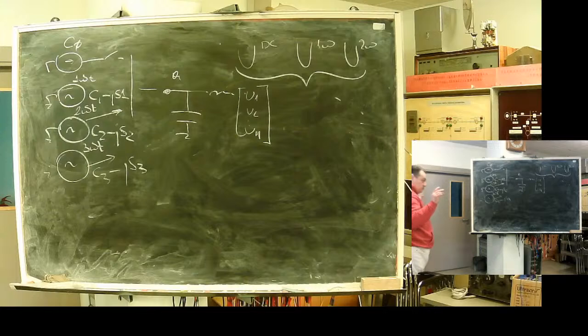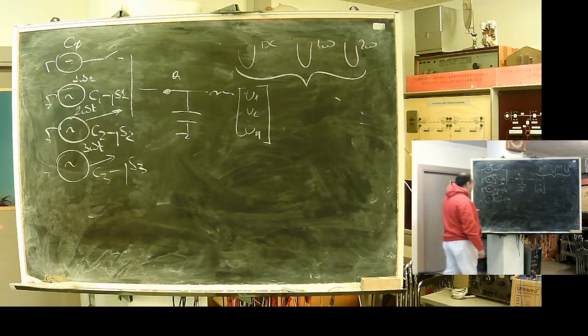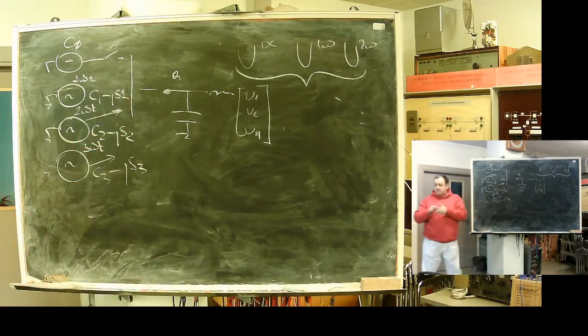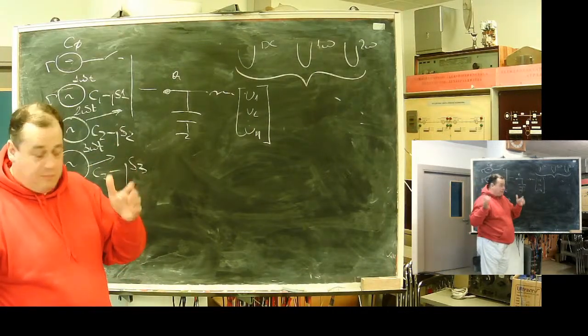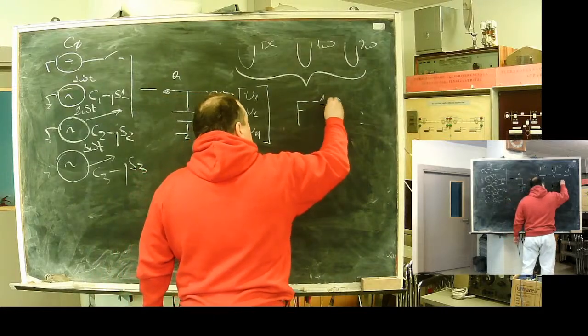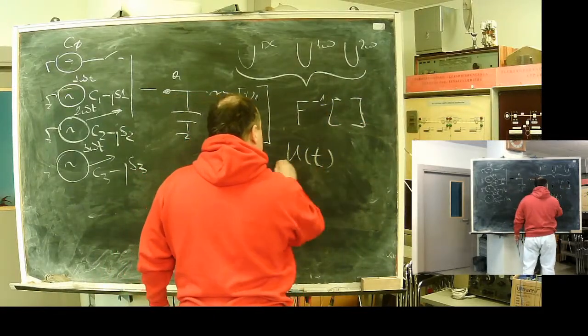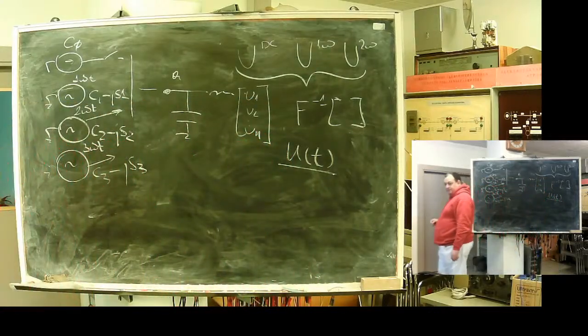So I can use the method of nodal potentials, nodal voltages, to solve my schematics in the DC regime, and at single, double, triple, and so on frequency. I will get a block of partial regimes. Applying the inverse Fourier transform, I will get real voltages as a time function. Decompose into ideal components, perform the calculation on ideal components in the world of ideal regimes, and then connect everything together with the inverse Fourier transform.